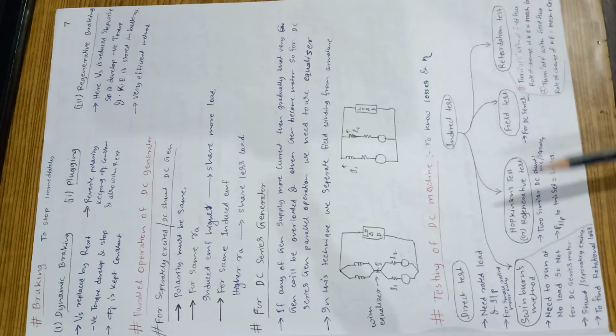The Hopkinson test is also called the regenerative test. In this we need two similar DC machines, shunt or separately excited.